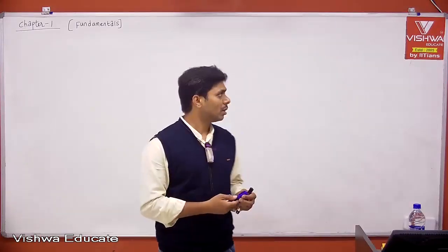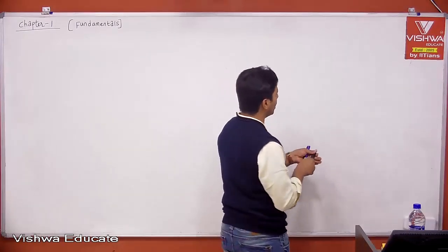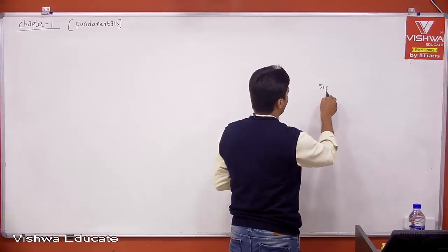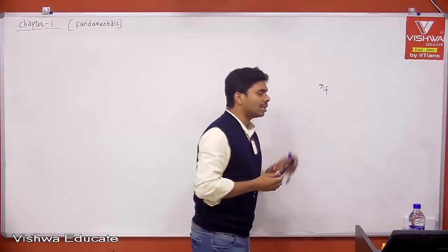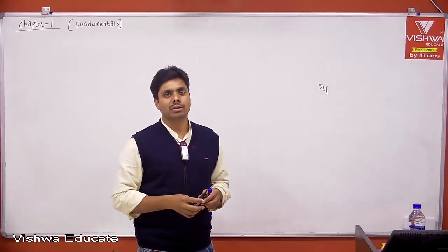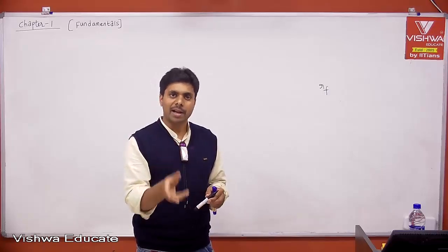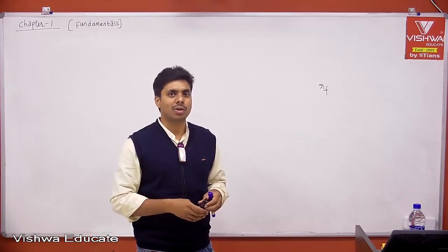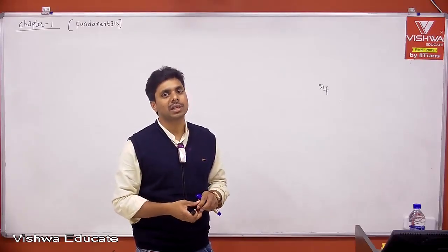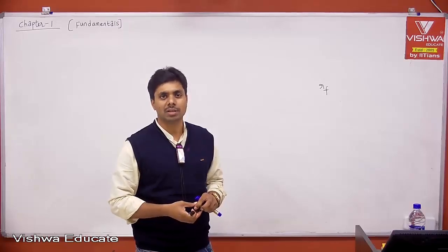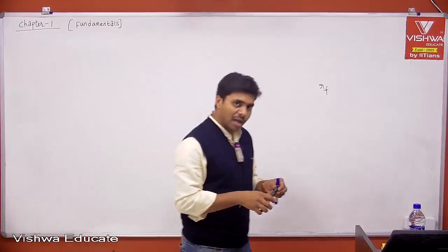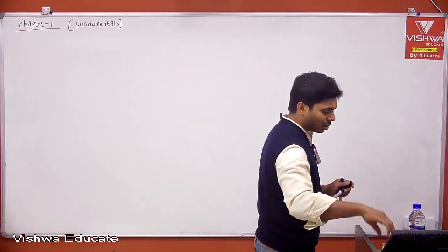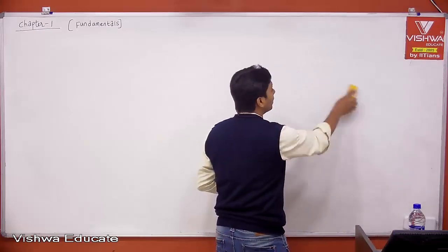That's why we normally represent forward resistance with a small letter, small rf. What is the meaning of small rf? Dynamic forward resistance. No need to attach the term dynamic; by default, that is dynamic resistance. We should not define static resistance for a PN junction diode because it is a non-linear element. I'll explain those points in detail later on, and it is related to resistance.